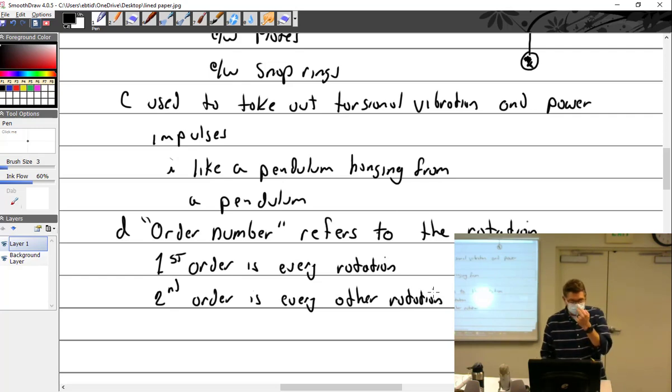And there's a service instruction, and it is lengthy. I want to say it's 20-some pages long, that lists every single engine and what the bushings and the pins are, and the weight and the part number of the counterweights, and then what order they are. It's really interesting to look through, but most of your Continentals are going to run 4th, 5th, and 6th order stuff. So it'll have like two 6s, a 4, and a 5. It's just kind of weird. I don't know how they come up with it. Well, engineering is how they do it.